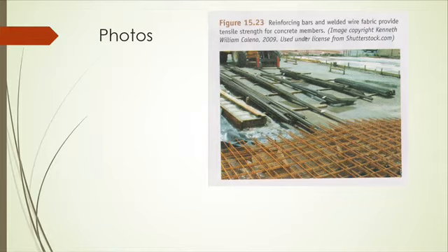So using smaller diameter bars may reduce the cost of renting a crane, but may require a larger number of steel bars being placed in the concrete. But using larger diameter reinforcing bar will reduce the number of steel bars in the concrete, which in turn avoids congestion in concrete and will prevent any segregation or honeycomb in concrete, which is very bad for the concrete integrity. So it's a pro and con, depends on the requirements.